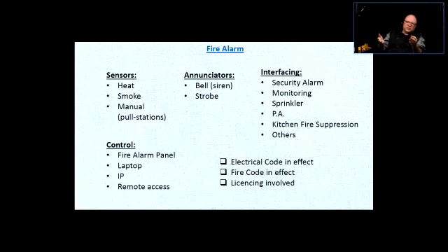There are certain systems where if one triggers, the whole thing triggers, and all the sprinklers are going to spread water. But it's a very rare situation. Usually the one that triggers is the one that is going to spray water and the other ones are not. What happens when the sprinkler system is triggered is that the pressure drops, because there's water under pressure in those pipes. If the sprinkler triggers, the whole pressure drops because there's an outlet for the water. So the pressure in those pipes is not going to be as great as if nothing was triggered. Right?